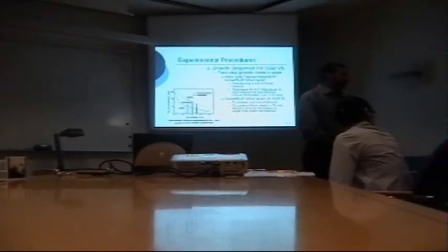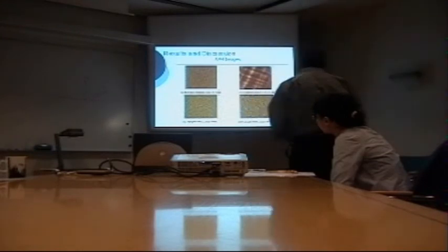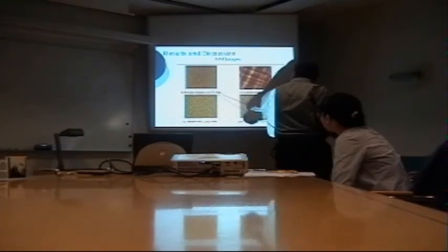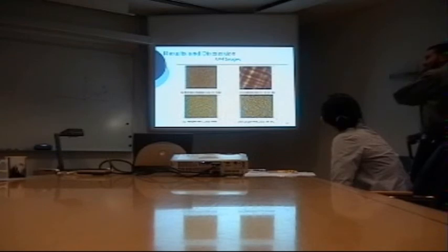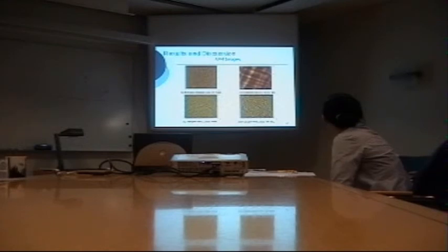In the AFM image where you were showing the nucleation patterns, there were some holes. I'm not calling these holes a fortress. What are these holes? These are basically pits. They can be a bunch of threading dislocations. How deep are they? We didn't check it basically. We did. They are about 30 to 40 nanometers deep. Is that close to the layer thickness? The total layer thickness is 70 nanometers, so it's around 50%.